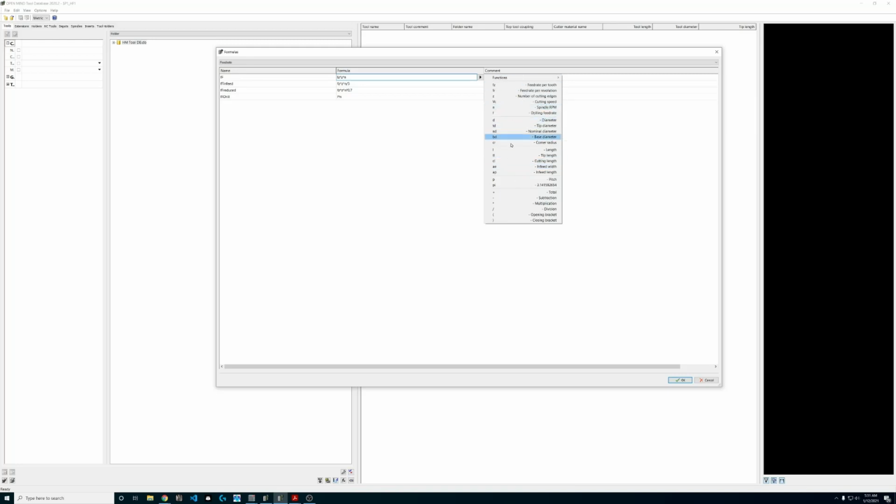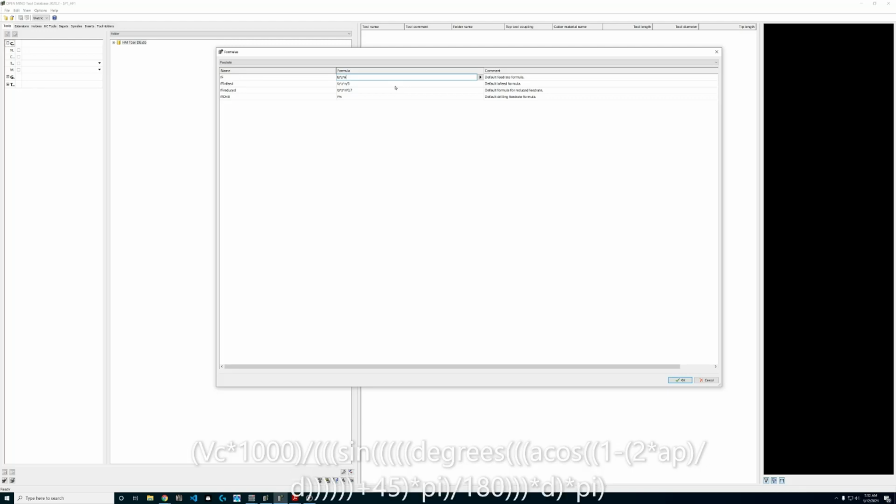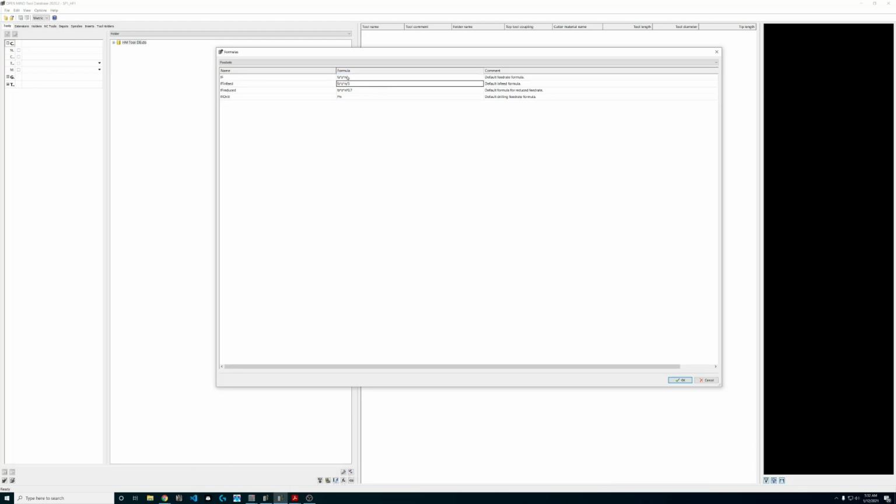So these are all values that we can use inside of the formula area. And it's pretty nice too when we apply things that don't work, it's going to turn red. We're going to know we don't have a formula in there. And furthermore, if we mouse over it, it's going to tell us kind of where the problem exists. That seems like not a big deal now, but once you see the formula for the effective cutting diameter of a ball end mill or bullnose end mill, it's pretty incredible how complicated that formula gets. It's important to know.